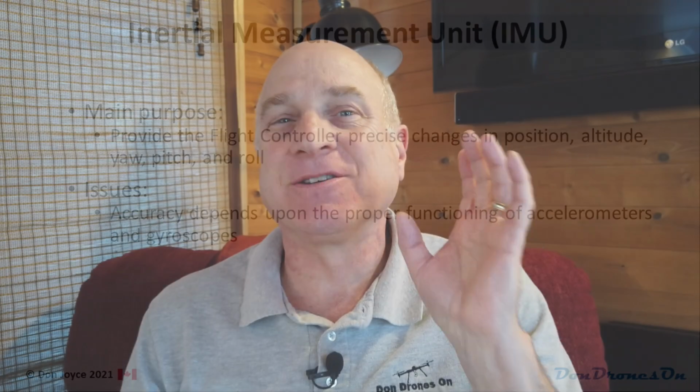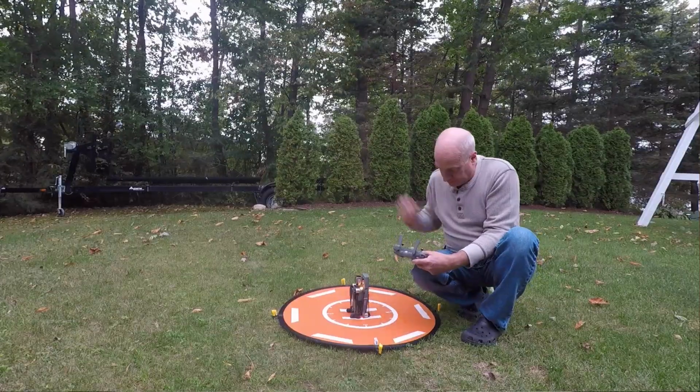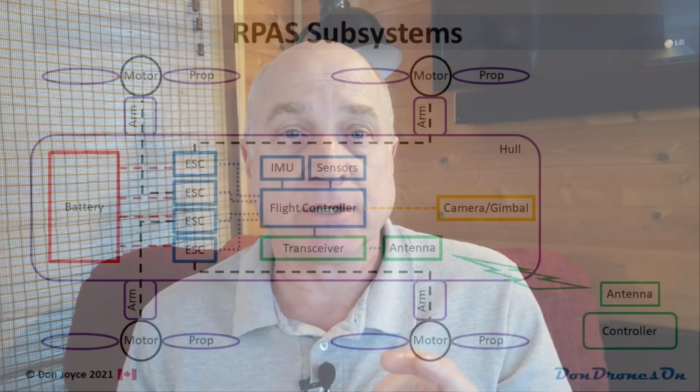For this reason, it is critical to recalibrate the IMU when the system suggests it and to do a recalibration periodically, even if your drone doesn't ask you to. Don't do it before every flight, but perhaps once a year, or if you see your drone acting a little strange, like drifting or not keeping a perfect horizon line. These are telltale signs that your IMU needs calibration.